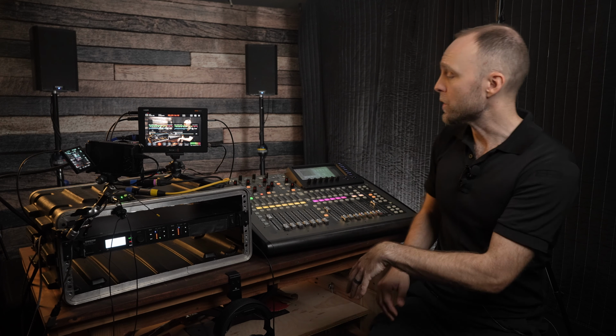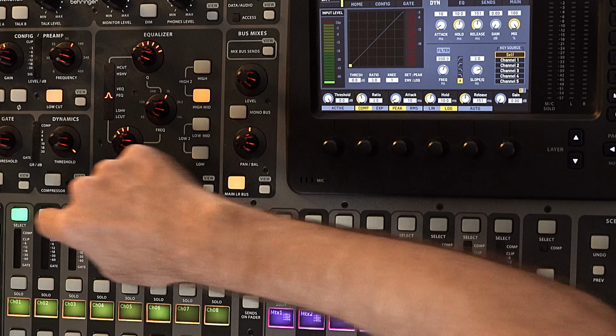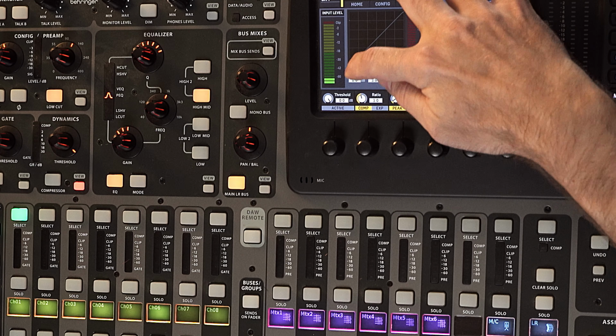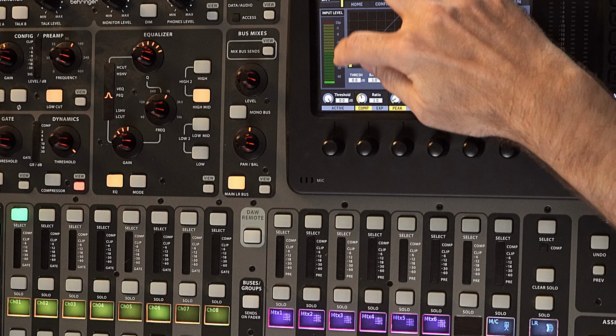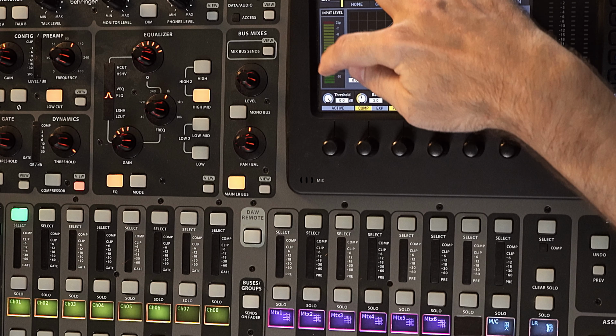And let me go back to this noisy audio real quick, because the result of this backwards method is that engineers are not only ignoring their audio meters and ignoring the actual electrical levels in their equipment, but this most often results in really low input gain on each individual microphone channel. And if we look at my microphone channel here, I'm on channel 1, we can see, even though I can hear this out of my PA decently well for this space, I've got very low input gain on this channel.